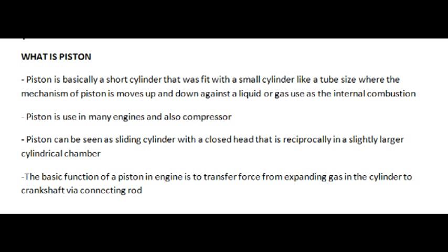A piston can be seen as a sliding cylinder with a closed head that moves reciprocally in a slightly larger cylindrical chamber. The basic function of a piston in an engine is to transfer force from the expanding gas in the cylinder to the crankshaft via the connecting rod.